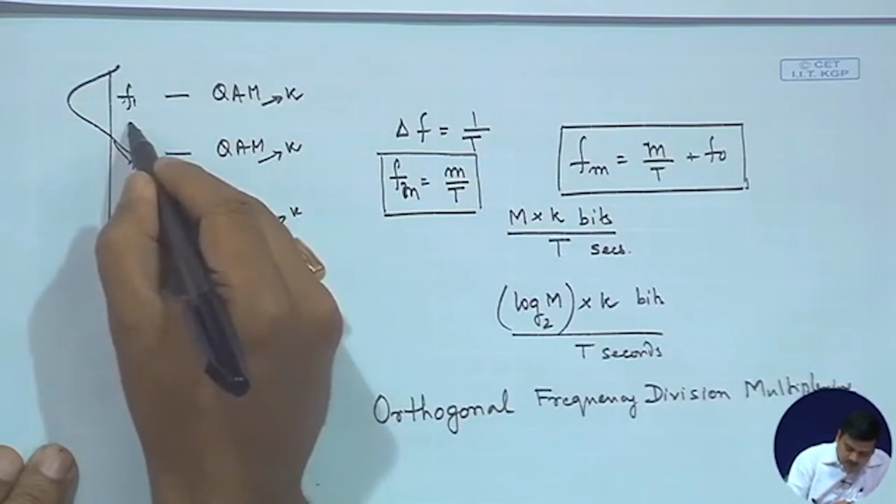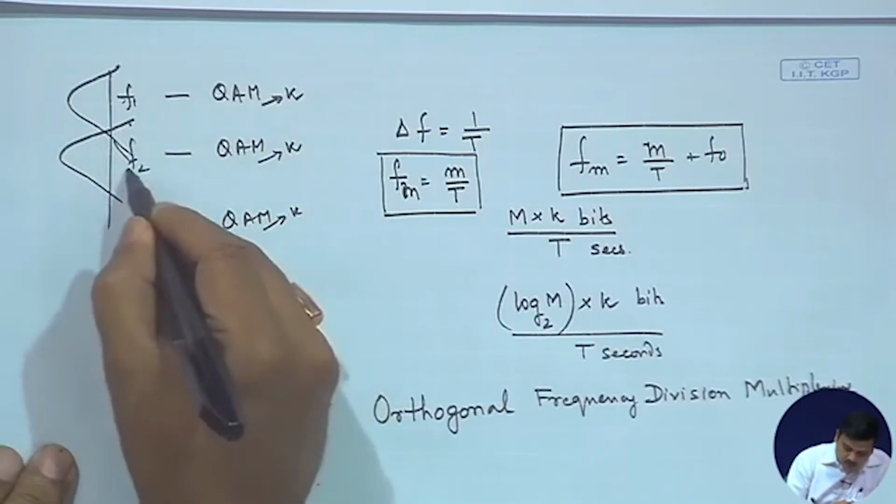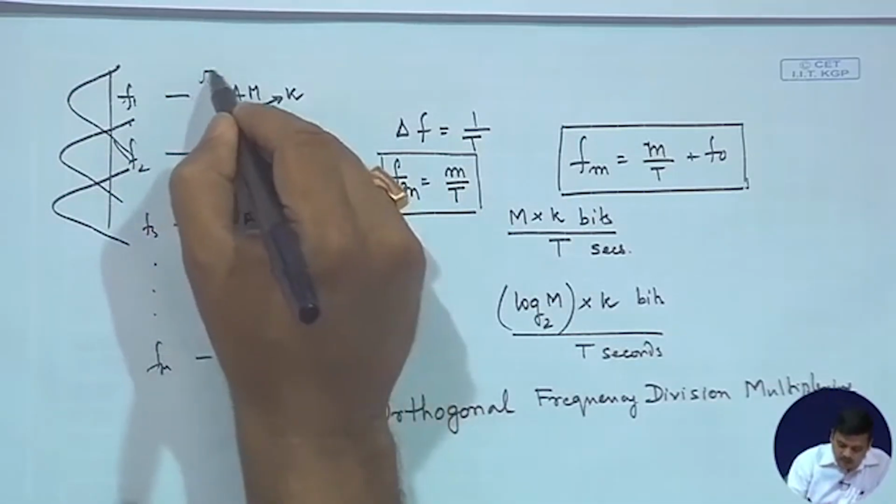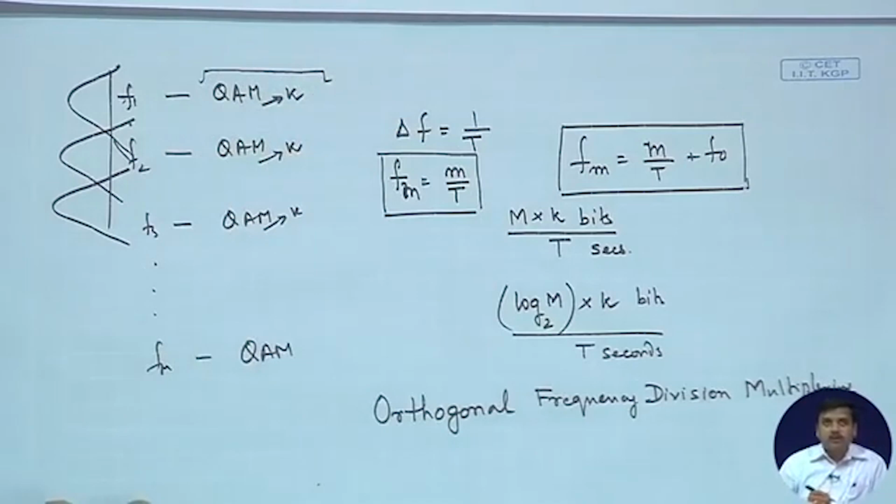So, you have a frequency spectra which looks like this, and provided our time domain pulse is a rectangular pulse. So, what we have in this case is the smallest frequency separation while doing frequency division multiplexing. You can't do any better than this, any smaller frequency separation, while maintaining orthogonality amongst the carriers, or sometimes called subcarriers.